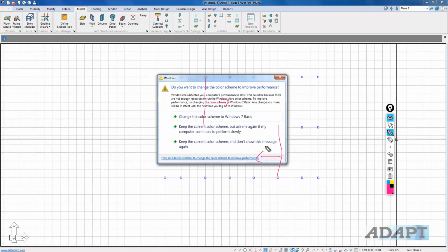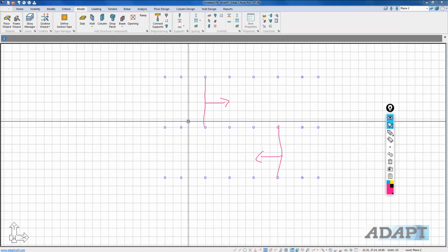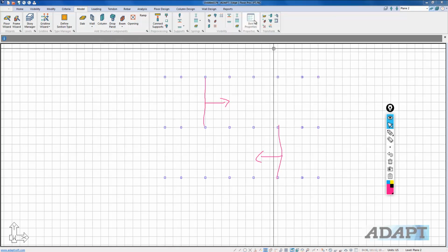So whenever we model a ramp, we're going to model that there's going to be 4 input points. The 2 points define the top of the ramp. The second set of 2 define the end of the ramp, and those are always defined at the level below the active level. So, for example, let me go ahead and model some slab here, and then we'll go back and add the beams here in a moment.